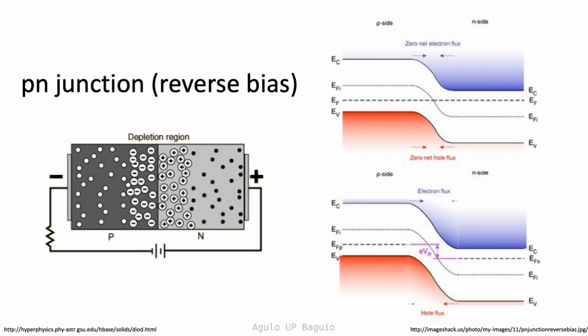barrier. In the energy band diagram representation, this is represented by the lowering of the n-type region with respect to the p-type region. This symbolizes the difference in potential between these two regions and shows the further increase of the energy required to bring electrons from the n-type to the p-type and holes from the p-type to the n-type.